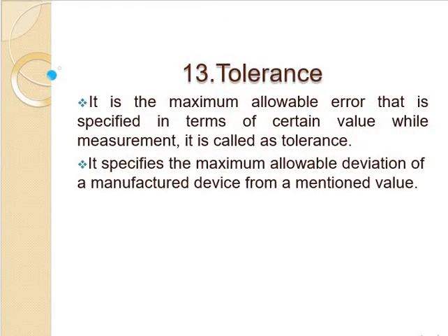Next we will see tolerance. What is tolerance? Tolerance is the maximum allowable error that can be specified in terms of certain values while measuring. Suppose we are measuring a job that should be 10 mm.